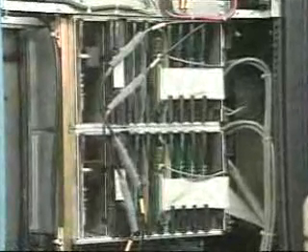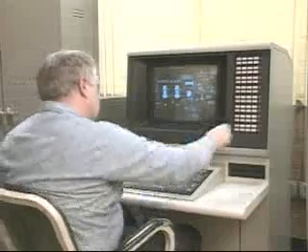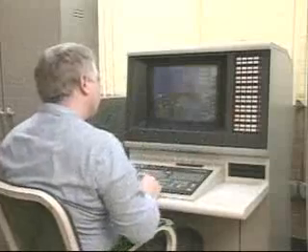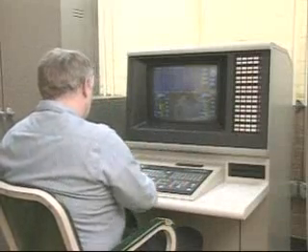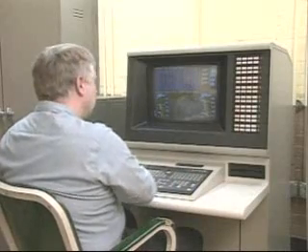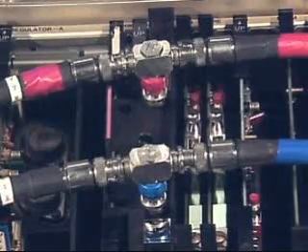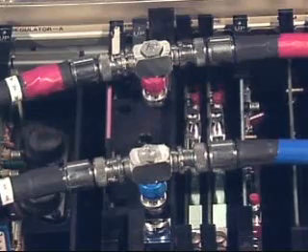These controllers can act independently. However, to achieve total process control, the controllers need information from outside sources, such as operator consoles and other digital controllers. The interaction between devices in a DCS is made possible by the use of a communication network.